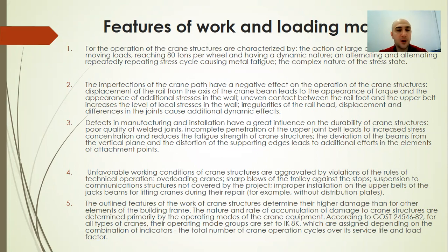Due to eccentric application of the vertical load and horizontal forces applied at the level of the railhead, an additional moment acts on the upper third of the beam, causing the web to bend. Vertical and lateral impacts of the cranes are dynamic in nature and are often accompanied by jerks and impacts.